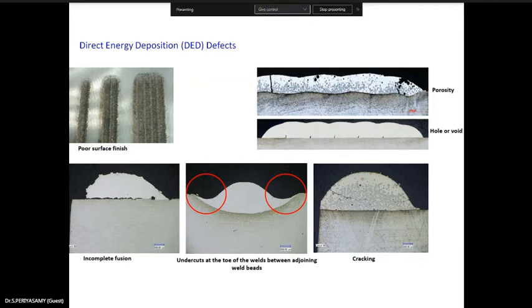So what are the tests you are going to do? That is either the shear test, compression test, tensile test or torsion test. That variation will be correlated with the internal material composition and the layer formation or the particle melting conditions. So either it's uniformly melted or not melted, or sometimes the powder particles may not be consolidated. Here you have enough particles that are separated.